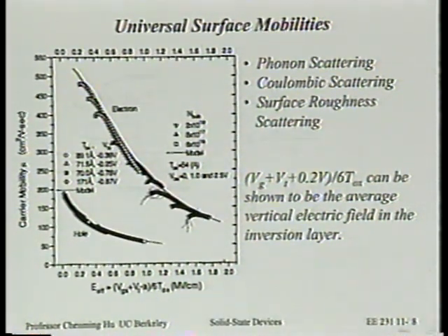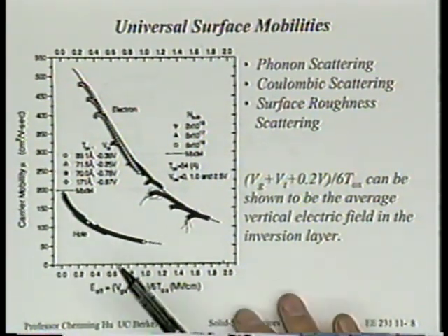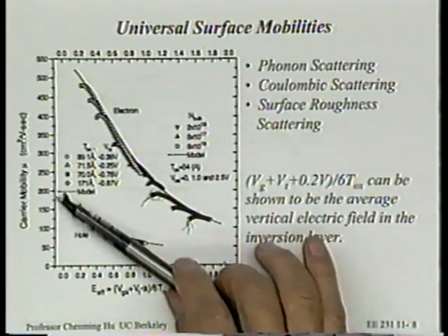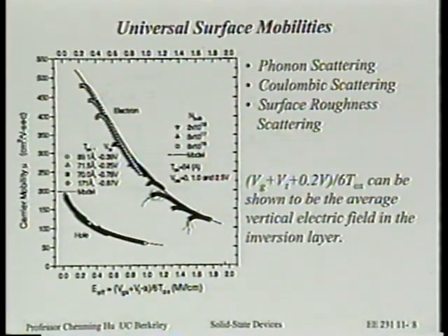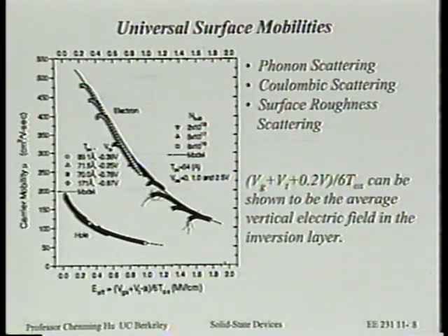All right? And also on this, we showed a different curve describing the mobility for holes. In fact, holes show an even better plot. We see less Coulombic scattering. Okay? In a way, it may or may not have to do with what you said about the noise, but it's a fact. We actually see less Coulombic scattering in the hole case usually. All right? Now, why is that the case? We're not too sure.